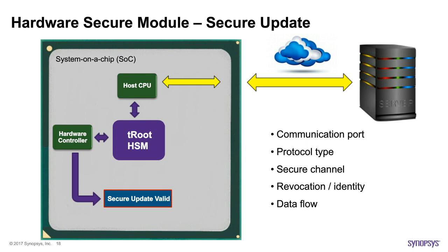So let's start with the communication port. How can this port be accessed? Will it be over the air or will there be a direct connect? Whatever the definition is, the important element to look for is how this information gets to the hardware secure module. And another question to ask: what if there's an on-board attacker who can observe it or change it? This is where a good protocol comes in. A good protocol will monitor the messages and provide a scheme that will ensure all the messages from each recipient were delivered correctly and intact, therefore eliminating any man-in-the-middle attack.